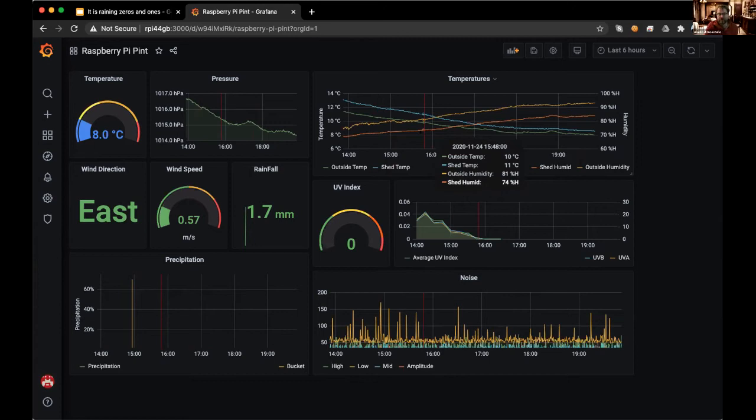And remember that the DHT22 really got unstable after half a year or a year of usage, and suddenly you couldn't rely on its values anymore. And it's dirt cheap, of course. So you can just stick it in. That's why a lot of people just put it on a pin, so you can just rip it out and put a new one in. But I'd rather have a proper chip like the BME.